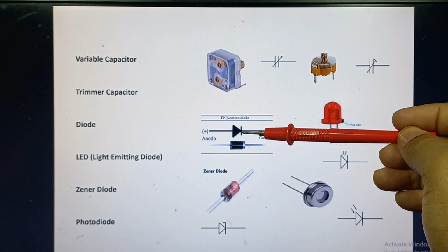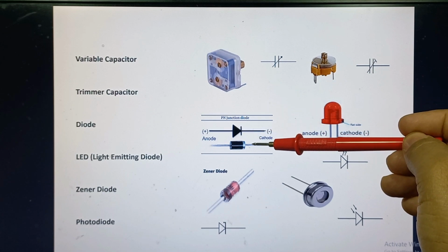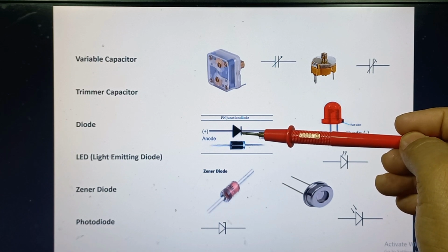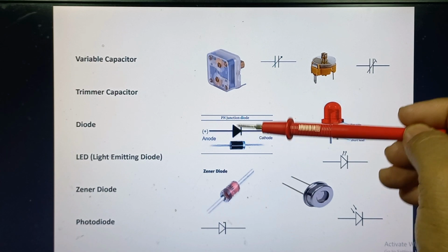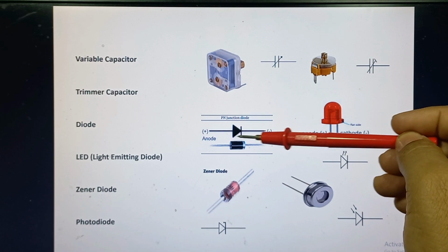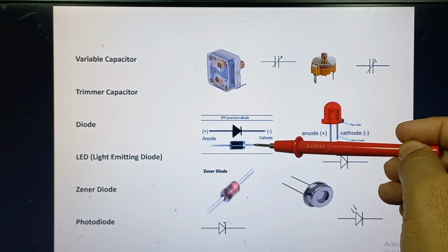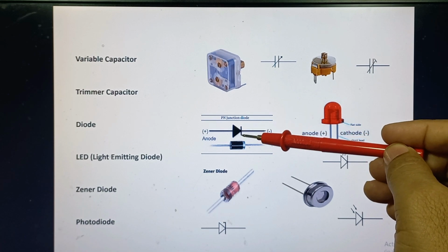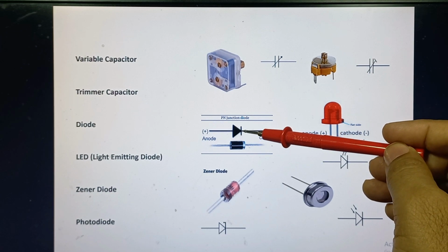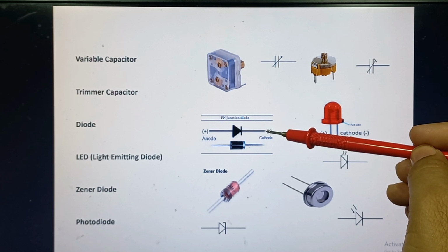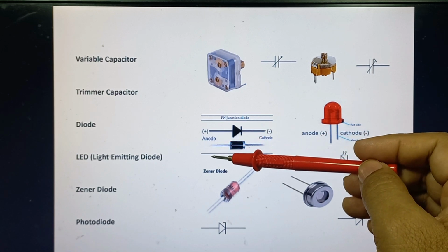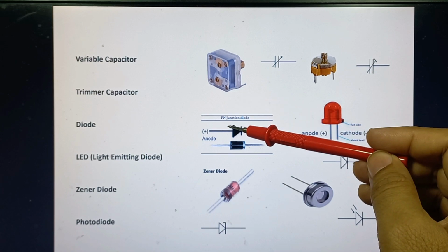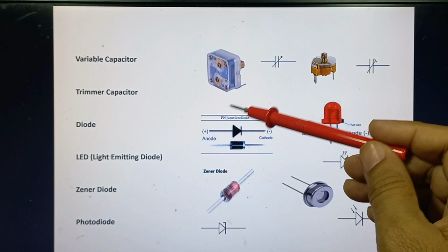It appears close to any terminal. This one is the closest terminal to this strip. It determines the negative terminal of that side. This one is the negative terminal of your rectifier. Here you can see also a strip over here. So this one is marked as negative terminal of a rectifier, and the other would be the positive terminal of the rectifier. The negative terminal is also called the cathode of the rectifier, and the positive terminal is also called the anode of the rectifier.